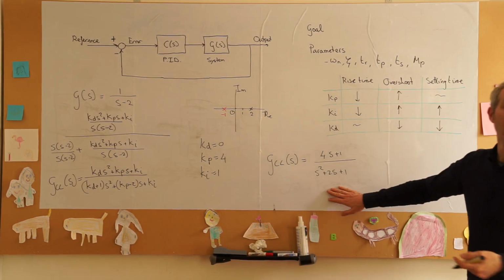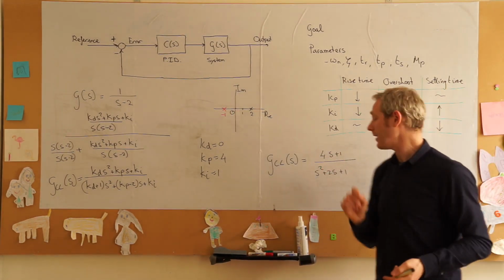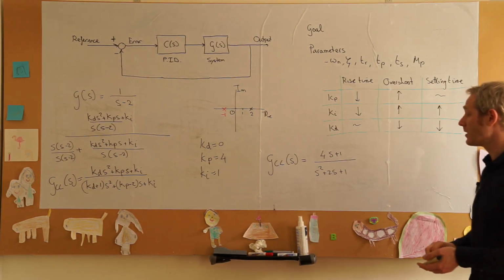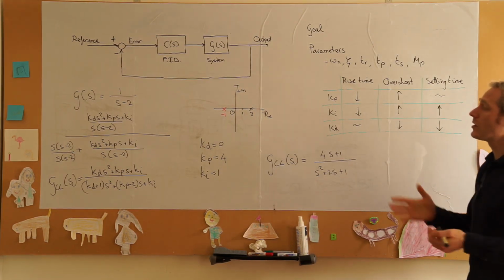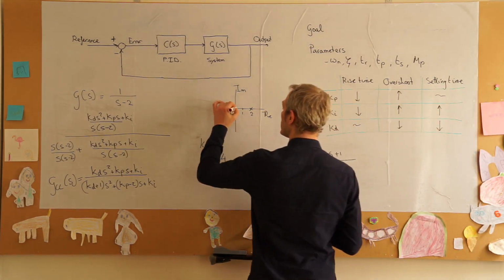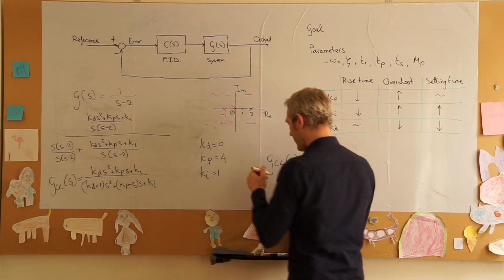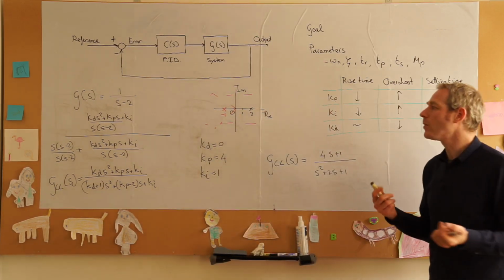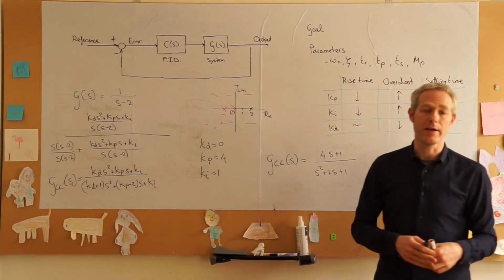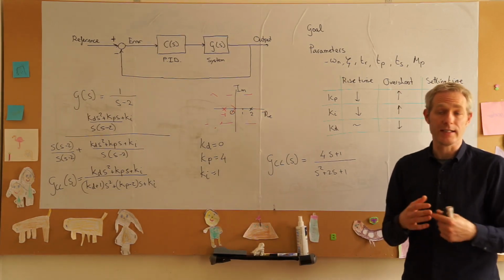So we have now the behavior we wanted. The poles are in the left half plane and specifically at -1, which has stabilized our system. Now we could have chosen our poles anywhere. We could have said, well, we want to have a certain frequency, we want to have a certain damping ratio, and these will all yield values for Kd, Kp, and Ki. Now, is this the way we do it when we design a system?